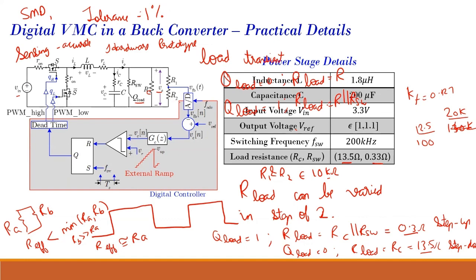That depends on the resistor you buy. There are certain resistors which come with 5% tolerance; they come with 5%, 2%, 1% tolerance, etc. If this is 10 kilo ohm and the tolerance is 1%, it would range between around 10.1 kilo ohm and 9.9 kilo ohm, so it is very little. But if there was 5% tolerance, it would range between 10.5 kilo ohm and 9.5 kilo ohm.